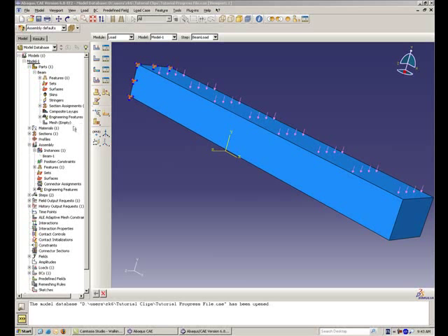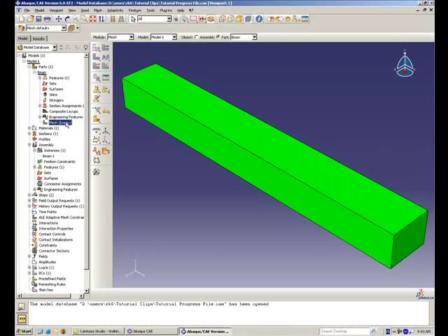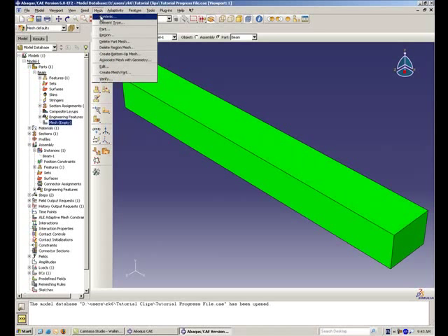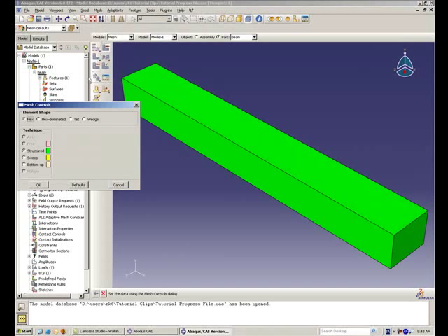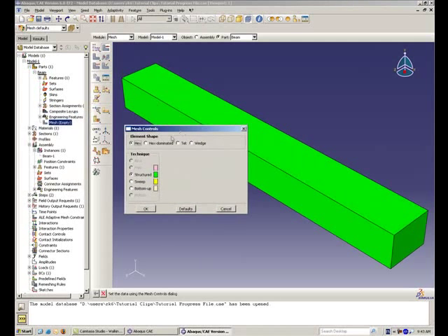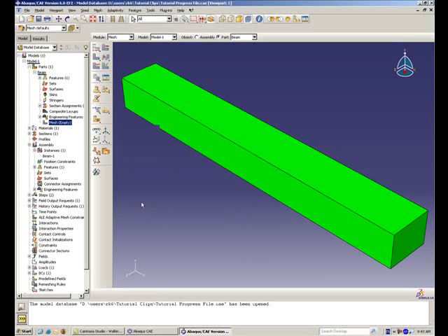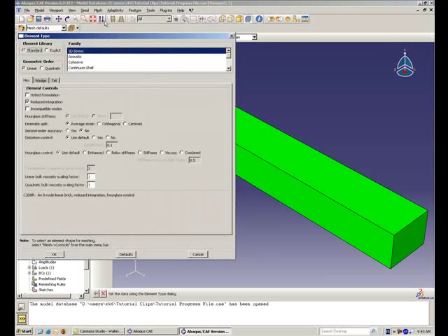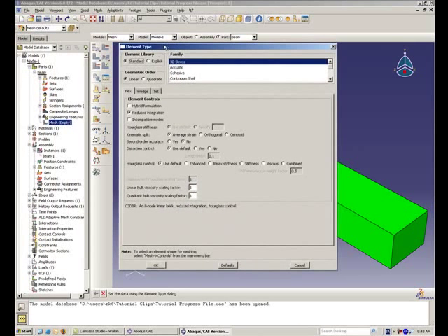The final step before starting the analysis is meshing the part. Start the process by expanding the parts and beams branches of the model tree, then double-clicking on the mesh container. Abaqus automatically switches to the Mesh module. From the main menu bar at the top of the screen, select Mesh and then Controls. Accept Hex and Structured as the default element shape and technique selections. Using the main menu bar again, select Mesh and then Element Type. Accept the standard linear and 3D stress defaults, but click Incompatible Modes in the Hex tab. Examine the Wedge and Tet tabs for future reference.